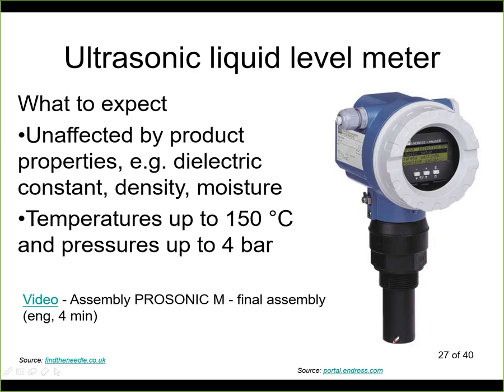Now this is the ultrasonic transducer, so it's a transmitter and receiver at the same time. Here we connect that with this thread, so you are also limited typically in pressure. So in terms of temperature and pressure, it is less performant than the other sensors, but it may work with applications where you have sediments and so on.